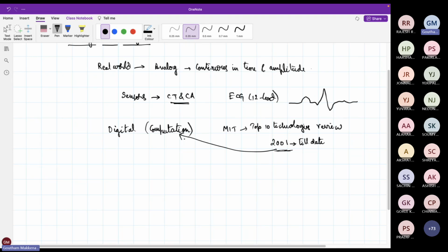Our real computation power is in the digital domain, but all the real world signals are in the continuous time domain. This is where analog IC design comes in. It acts like an interface between the real world and the digital world, where we convert the given analog signals into the digital domain. That might be a better introduction to an ADC based course, because the ADC is the actual module that converts the continuous time and continuous amplitude signal into discrete time and discrete amplitude signals.